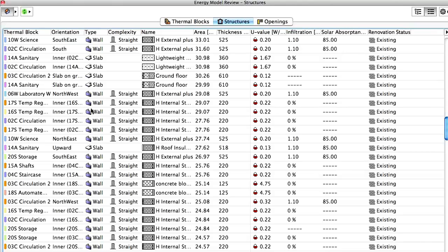All these values and properties can be modified or customized, and the corresponding building elements can also be instantly visualized in the 3D view. Most of the other building energy software applications require users to remodel the building from scratch and to manually provide such calculation-related element properties. This requires a lot of time and money. EcoDesigner Star automatically extracts all energy calculation-related element data from the ArchiCAD building information model.